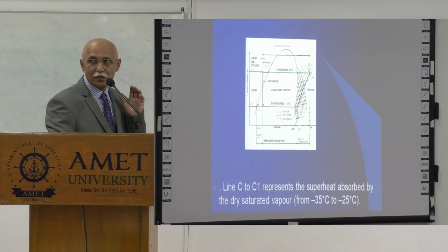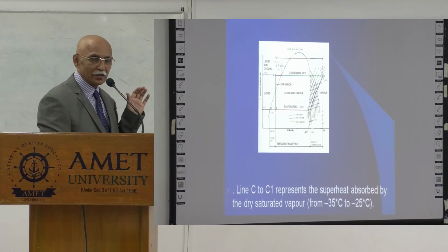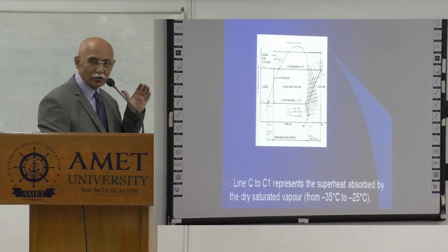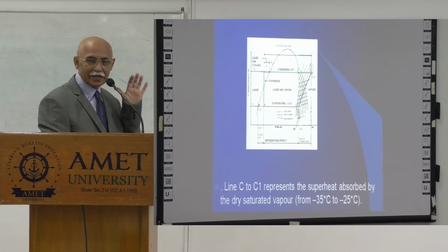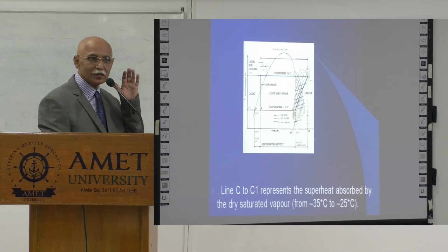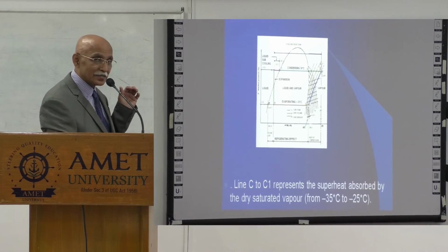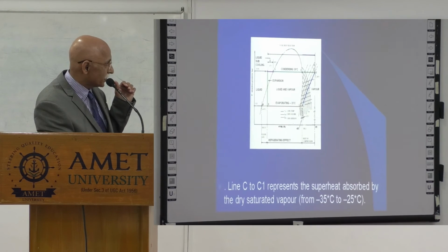Now the hot gas from the compressor is going to enter the condenser, where it is going to liquefy. Repeat, now it is going to cool down and change state in the condenser. So definitely the cooling down is going to result in a lowering of the energy levels in the gas or the liquid, and thereby a lowering in enthalpy. So you can see over here, the condensing is at a constant pressure. So when it enters the condenser, the energy keeps dropping. It converts into liquid. All this is at a constant pressure over here.